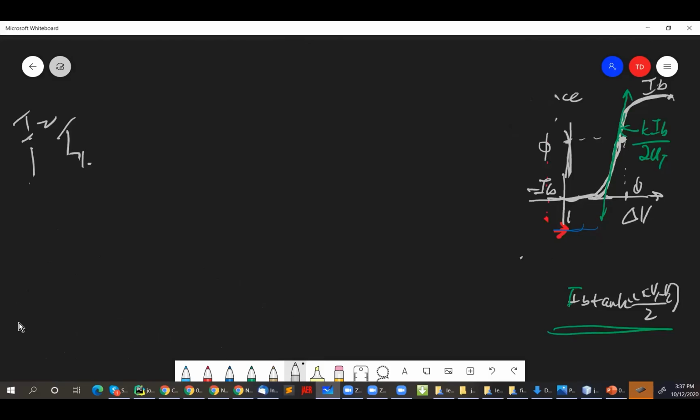Okay, so I think the final circuit that I should go into is the bump circuit and the current correlator circuit. I think you do have a current correlator exercise this week. So what's a current correlator circuit? One of the functions that's used a lot in neuromorphic circuits is looking for similarity between two input currents, sometimes also between two input voltages.